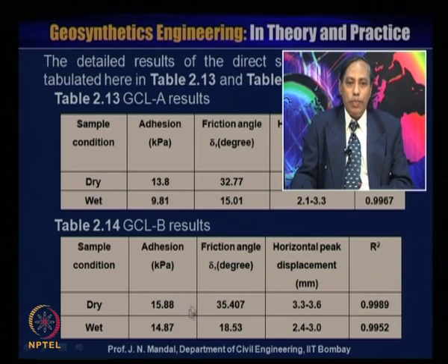The adhesion factor is 15.88 kilopascal for dry and 14.87 kilopascal for wet. The friction angle is 35.407 for dry, and for wet it is 18.53. Then the horizontal displacement is 3.3 to 3.6 for dry, and for wet it is 2.4 to 3.